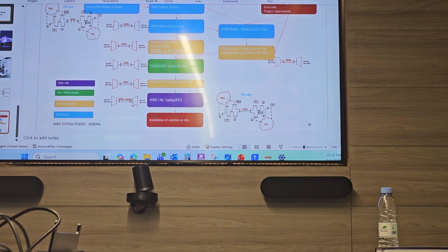So I explained grid following. In grid forming, you want to have, for example, a battery storage system. In case of blackout, something will happen. You want to be able to bring voltage to either 10 kV to 132 kV, and the system has to behave like a generator. Grid following cannot do this, but this needs to follow all this. It's a really challenging thing, I would say.